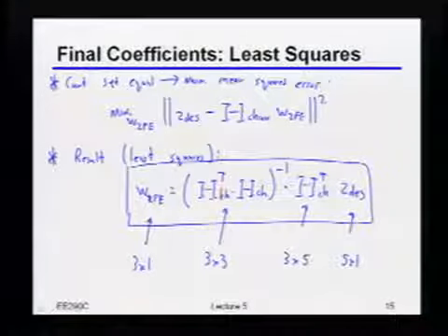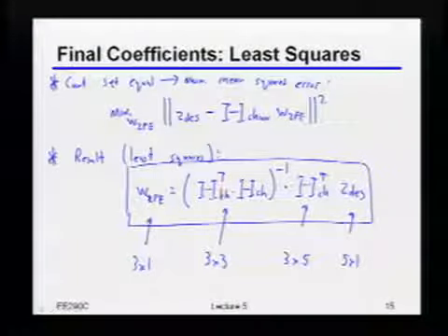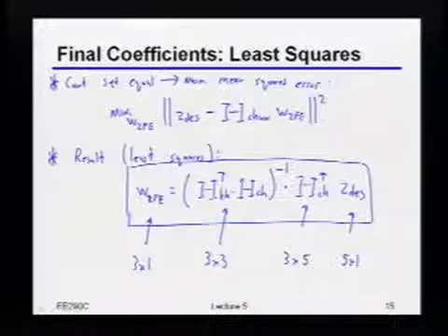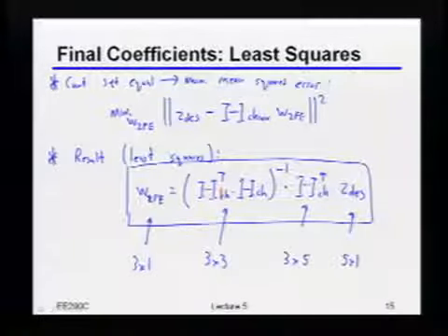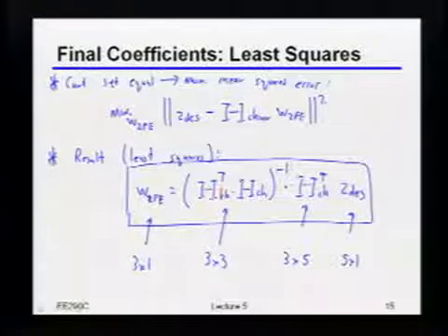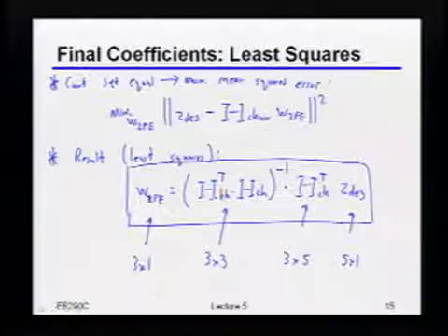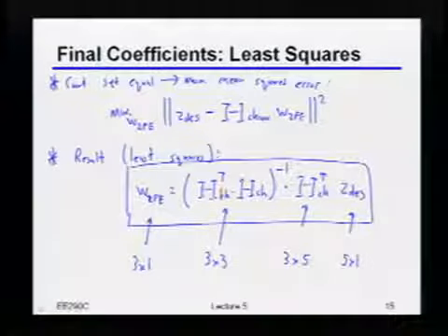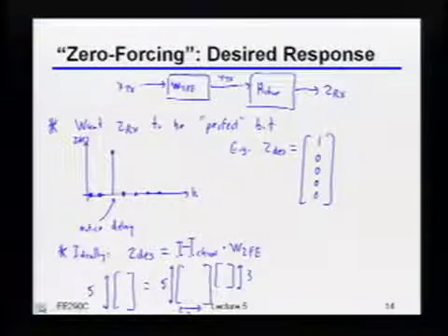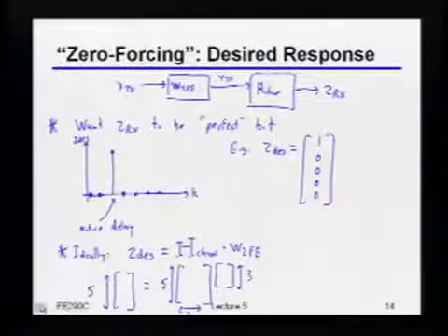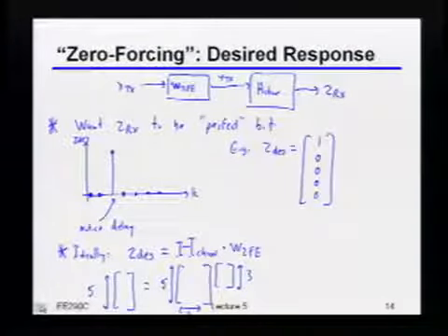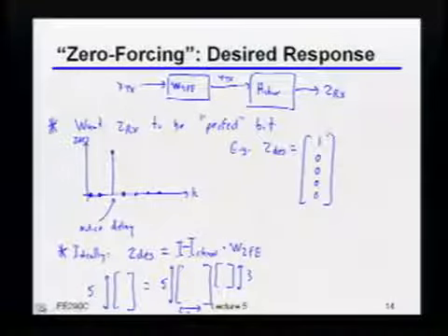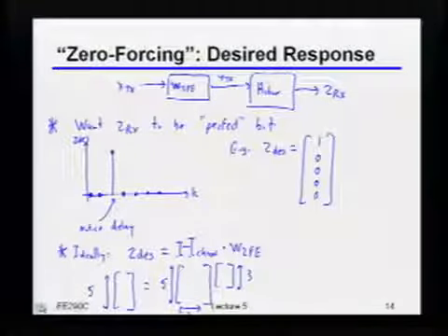How do you choose the number of taps in the filter? That's up to you. I've said nothing about what that is. You have to arbitrarily choose it right now. So you're just saying if it's long enough, you can actually solve the equations. Well, it depends on what exactly the channel looks like. But you are right that there are cases where you can directly solve for it. There are channels with some number of coefficients where you could just directly solve for the coefficients that